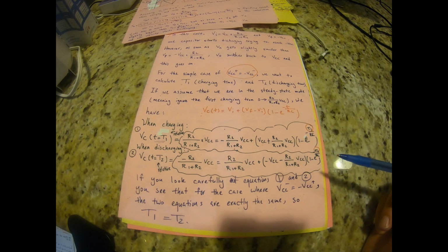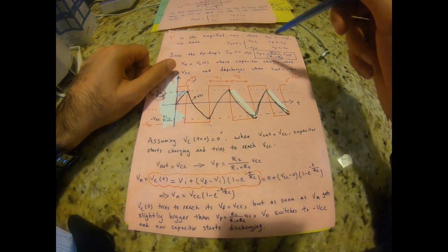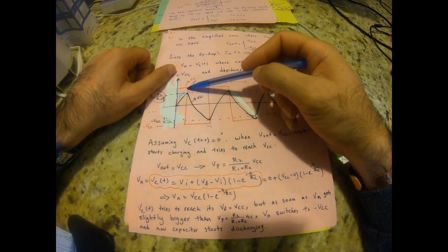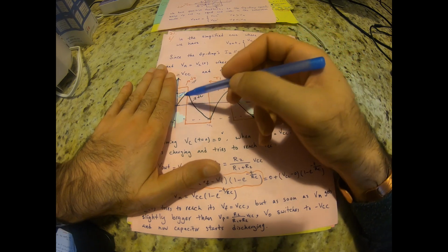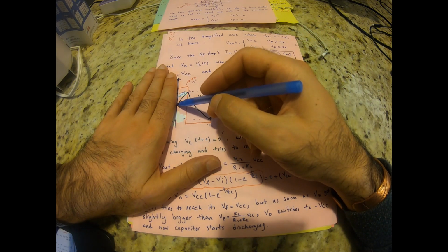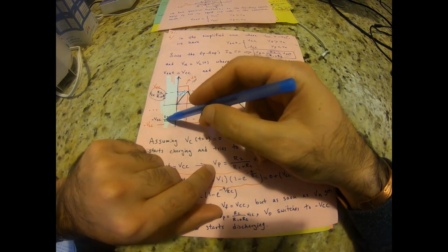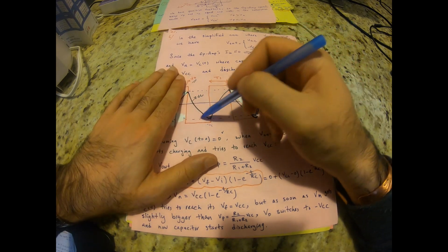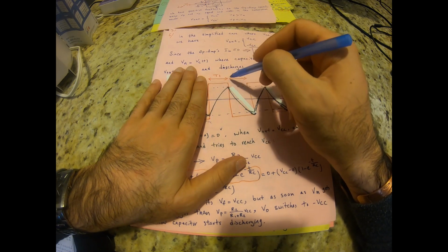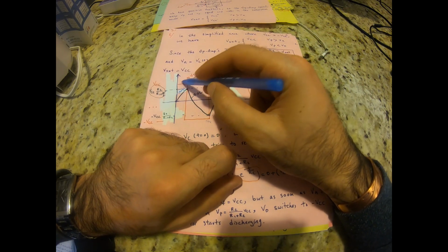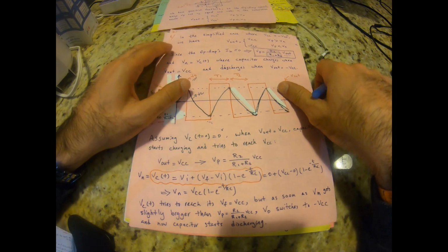One thing I forgot to mention is that we assume that our circuit is in the steady state. It means that we ignore the first charging time, because our capacitor starts with a 0 voltage, right? But from the next pulses, they always start from the negative voltage, right? So we assume that we're already in the steady state, so ignore this one. That's why I calculated T1 here and T2 here. I didn't calculate this one because that wouldn't be full T1. But this is the same as this T1. This is the same as the next one, and so on.